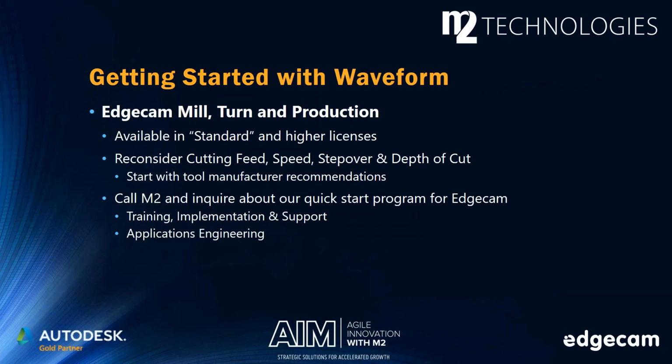Okay, so final thing before we get to questions. How do we get started with waveform? The waveform technology is available on EdgeCam's mill, turn, and production licenses. Production systems combine mill and turn together into the same license. So as long as you have a standard mill, standard turn, standard production, or higher, maybe advanced or ultimate, you've got waveform already. So if you're getting ready to start using it, just put it to use. Begin using it. For turning tools, you'll need a full radius tool. Could be a groove tool, could be a full radius ball mill, or full radius insert, I should say. And then from there, you just want to think about speeds and feeds.